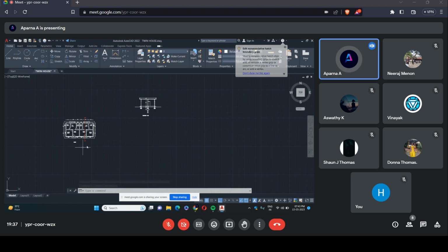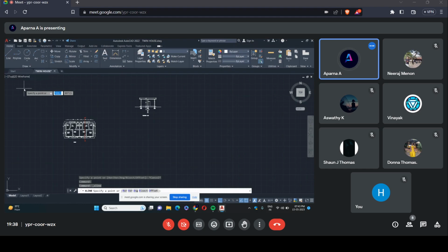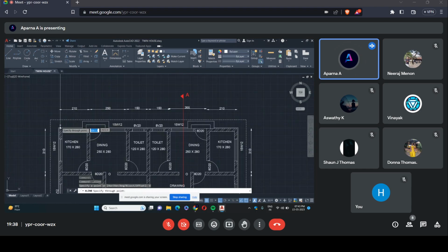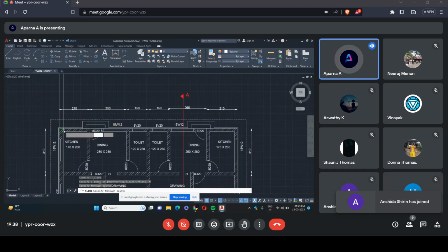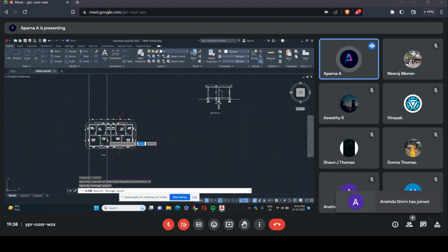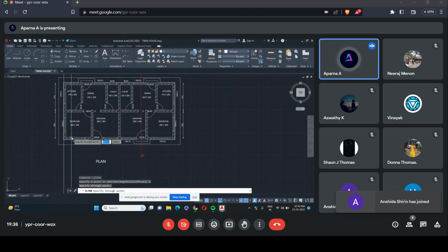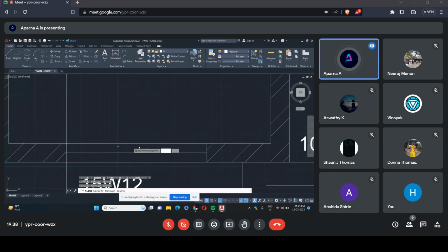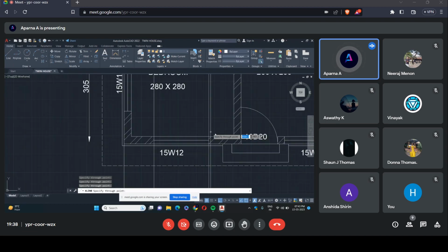For that I need to project lines from plan as well as section. I can choose construction line for that. So first I'm drawing vertical lines. So we end up in elevation. I can see the outer wall but not the inner wall. So in front elevation I can see these window, the door and step, not the inner walls.